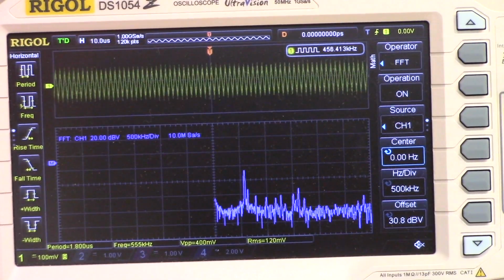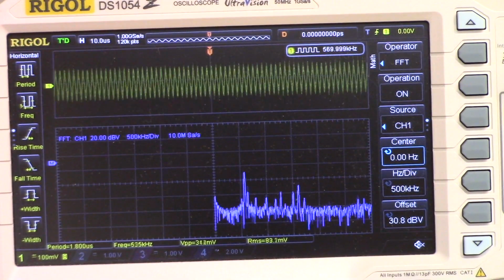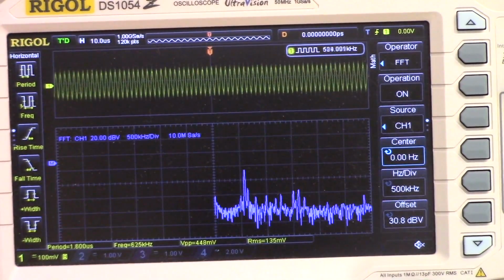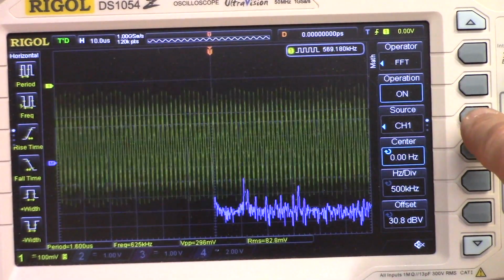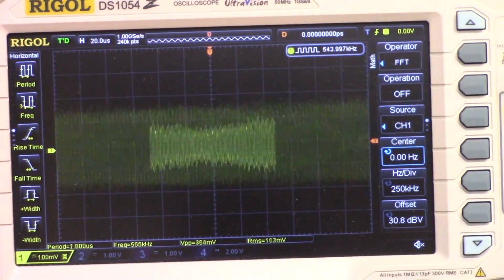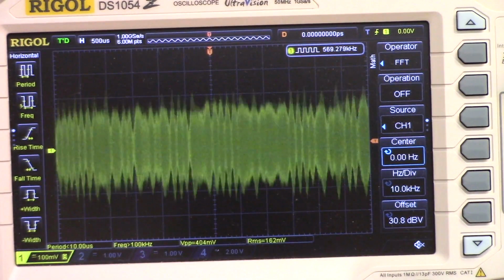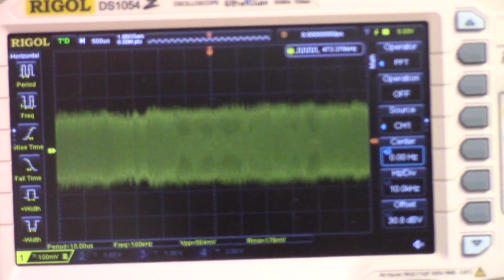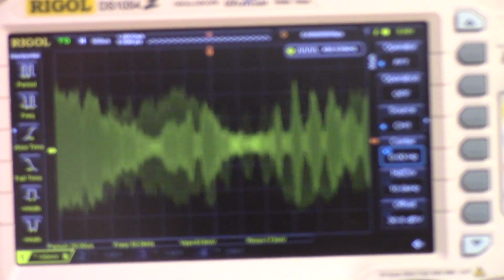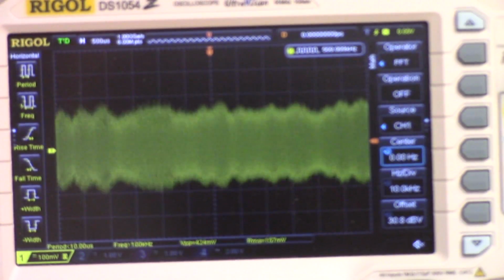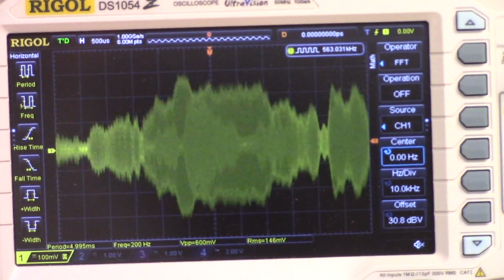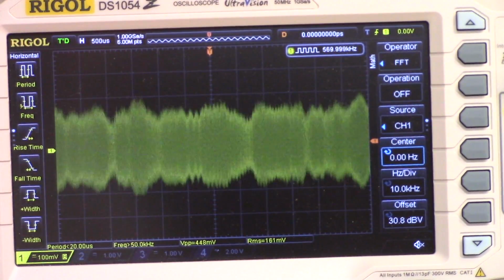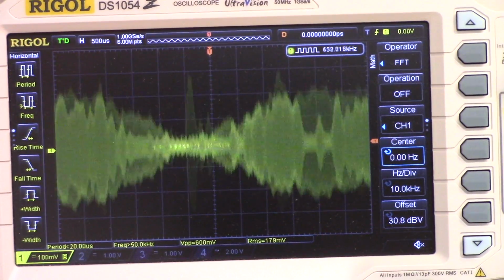Now, let me turn the Fourier transform off so we can get a better picture of the time series signal. So you can absolutely see how we've preferentially picked out the one signal at 570 kilohertz, and that is the modulated carrier wave, the modulation being due to the audio signal fed in the microphone in the studio.